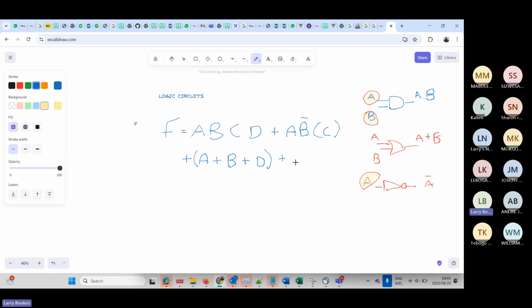Okay, so here let's use C or D not. Okay, great stuff. We're ready now. So from here we can see that this is your AND gate. Remember, this is the AND gate. So this AND gate has got 4 inputs, A, B, C, D, right? So it's gonna be a 4-input AND gate. It's so nice that you can just use this AND gate and then make as many inputs as possible in this course. All right, so it makes it easier.